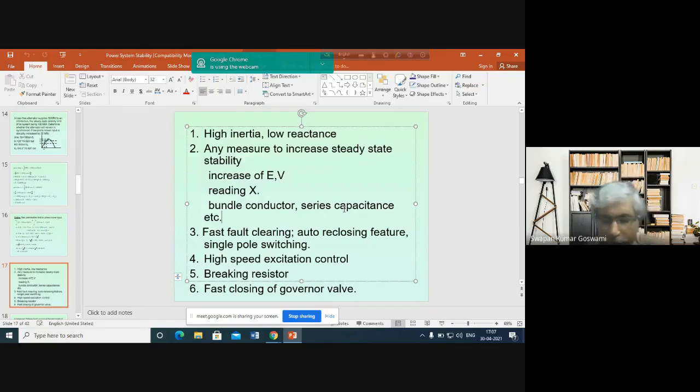They are multiples of the frequency. If 50 hertz is the fundamental current, then 100 hertz is the second harmonic, 150 hertz is the third harmonic. Generally in a power system, even harmonics are not present because of the symmetry of the waves, and odd harmonics will be present: third, fifth, seventh harmonic. That means 150 hertz in a 50 hertz power system, 250 hertz for the fifth harmonic, 350 hertz for the seventh. But sometimes there may be the flow of subharmonic current as well. That means harmonics which are less than 50 hertz are subharmonic. These currents also may flow.